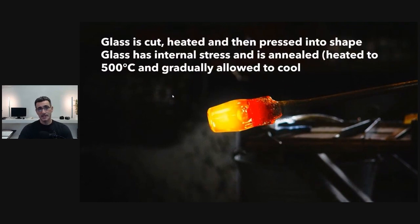Now, once the glass is melted, they often will pour it in sheets, break them up again and actually remelt them, and they'll take a little globule of glass and press it into a mold, so that at least they get the general shape of what they need. And then they anneal it, and annealing is relieving the stresses in the glass.